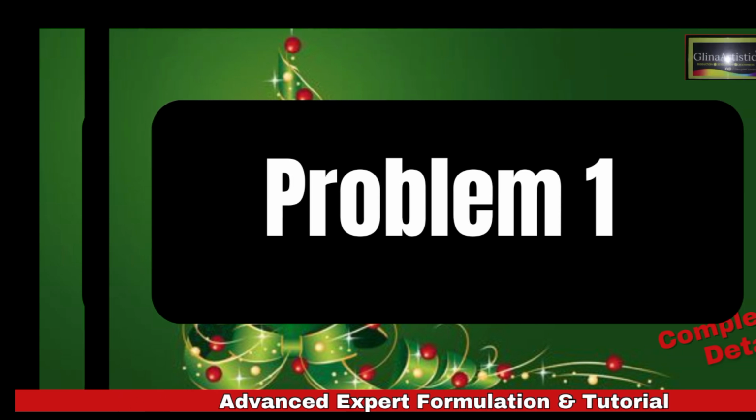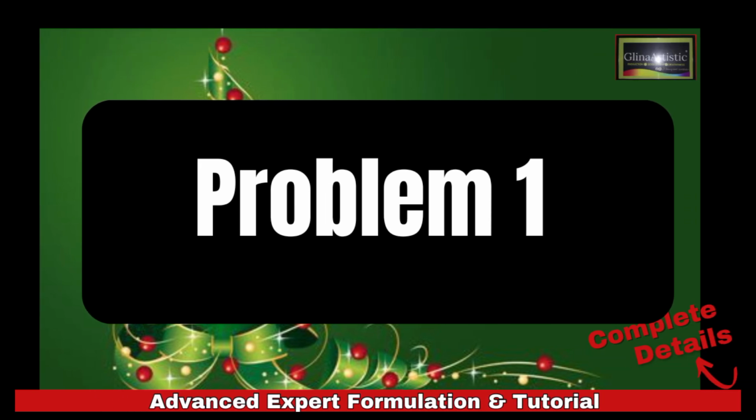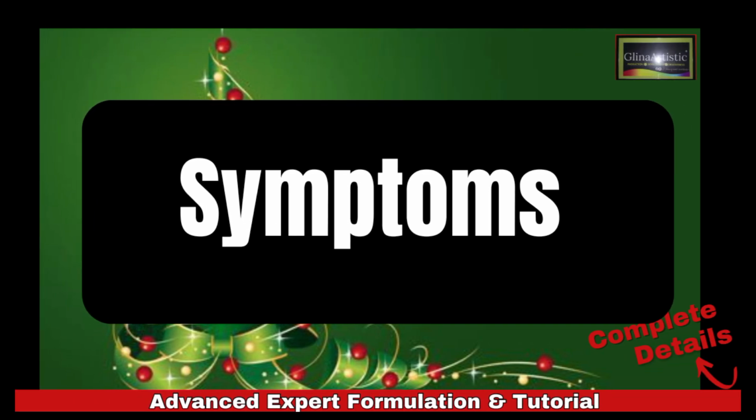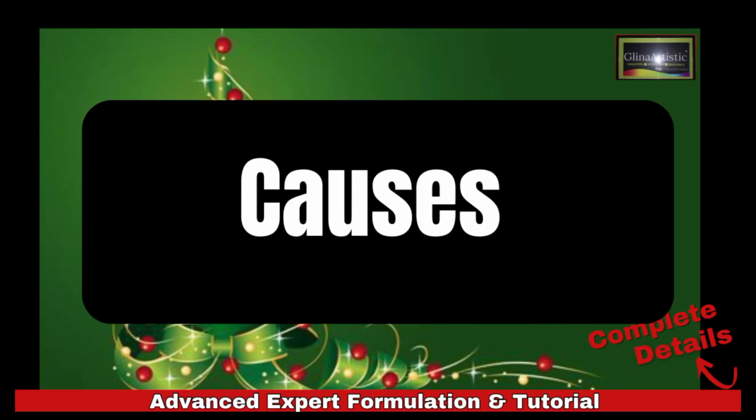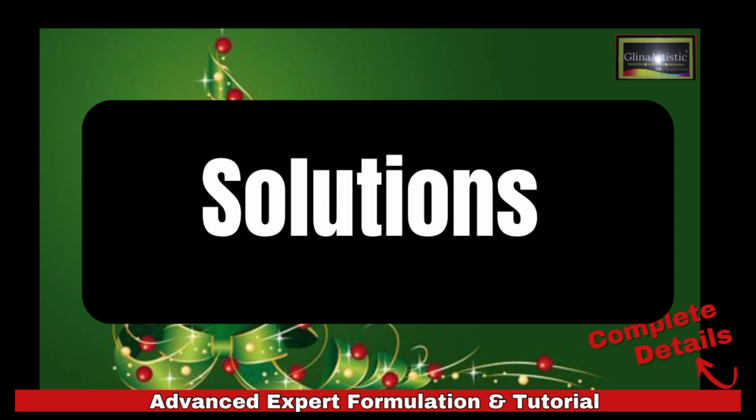Problem 1: poor dispersion of pigment. Yes, uneven color or clumps in the paint. So, what are the causes of it? Insufficient mixing or inadequate wetting of the pigment. And the solution: 1. Use high-speed mixers for better dispersion. If you cannot use a high-speed mixer, that is your hand mixer, you can make use of your stirrer. Make sure you stir very well. 2. Add a dispersing agent like your carbon PT to smoothen down your pigment.